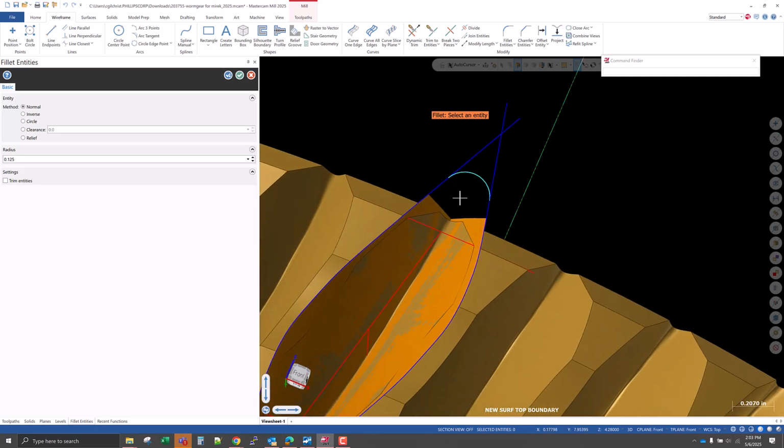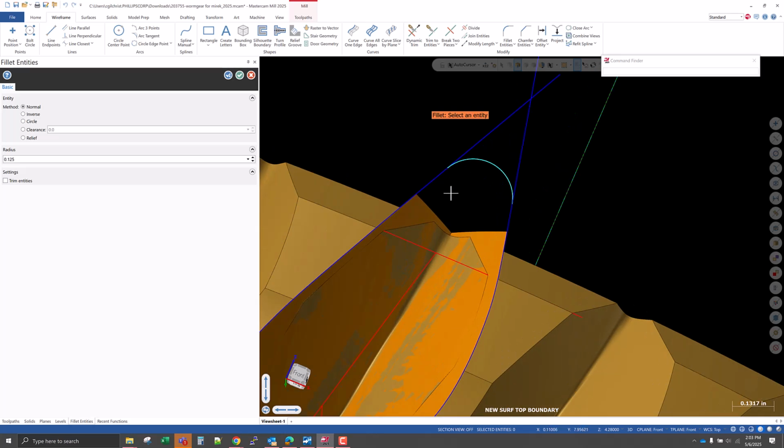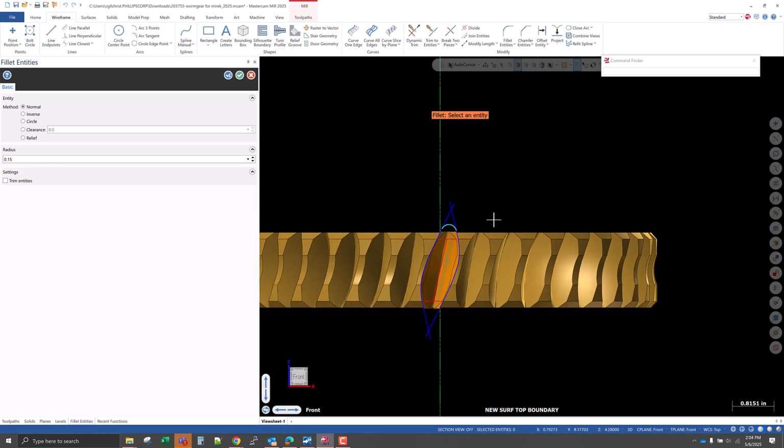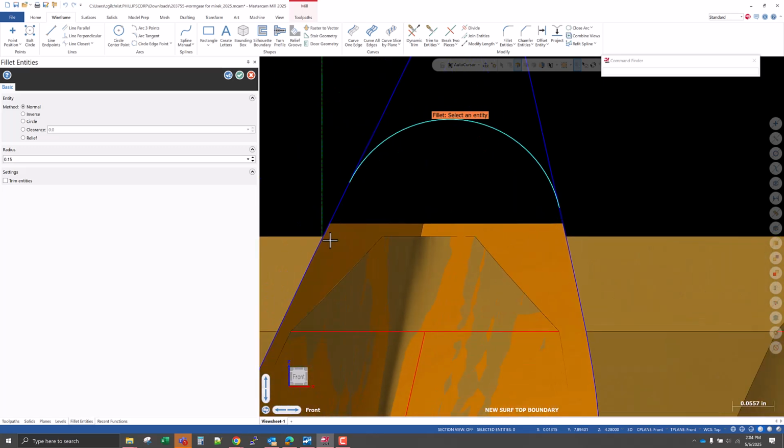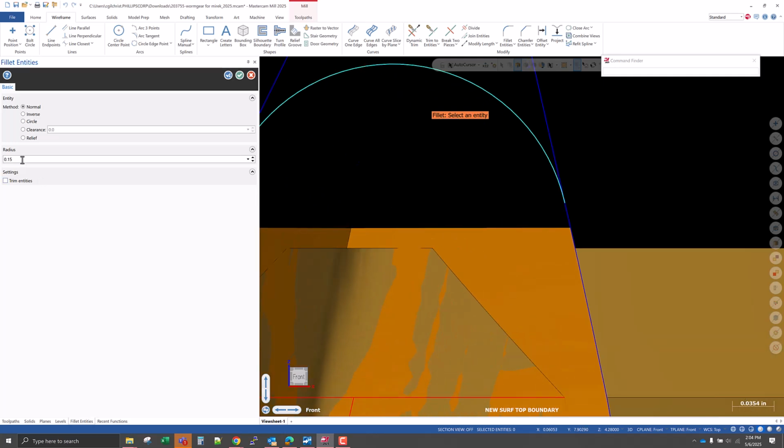And so what am I looking for here? I'm looking to make sure that the fillet that I'm using is bigger than the radius of the tool that I'm going to drive in there. So this should technically allow me to drive a 250 thousandths end mill. But let's edit this. I'm going to make it 150. Let's look at this from the front view. Yeah, we're getting there, and I'd love to have a nice little smooth transition from side to side. I mean, if I do 180, it's probably a little too big.